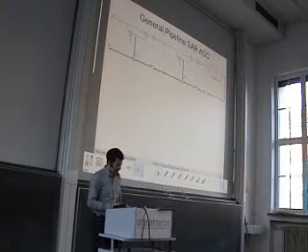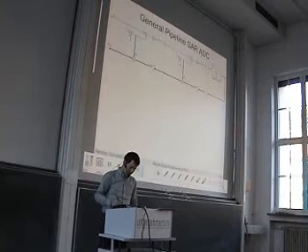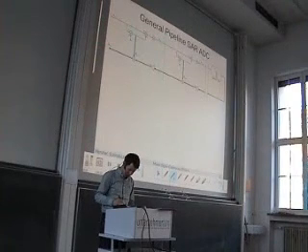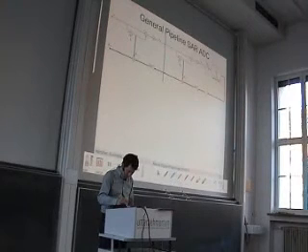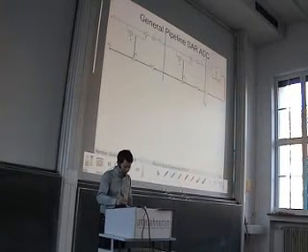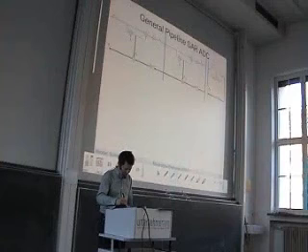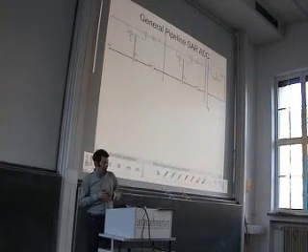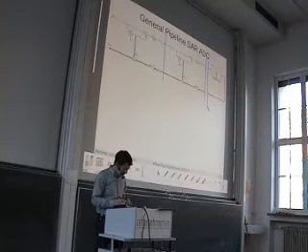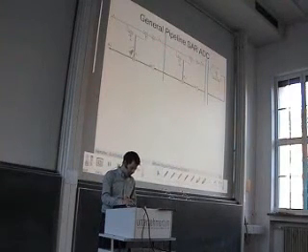And this gives us a circuit like this. So we have a first stage, then we have a second stage, and so on and so on. And finally, we have really a back-end ADC, which is not subdivided anymore. Out of each stage, we get our output bits.